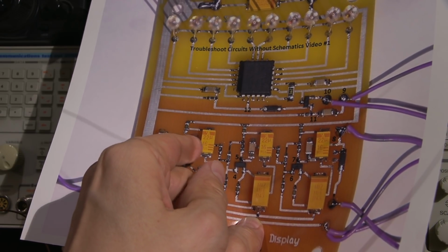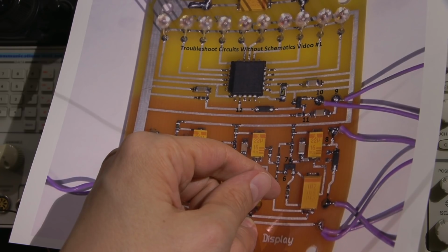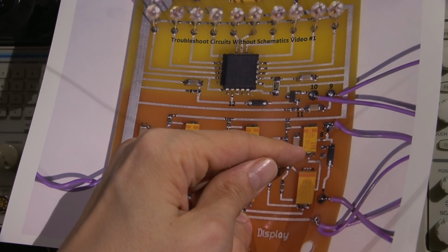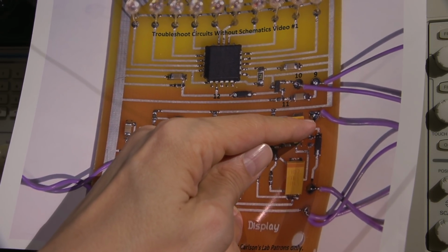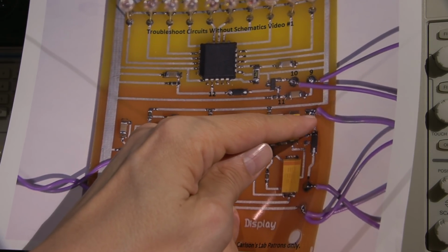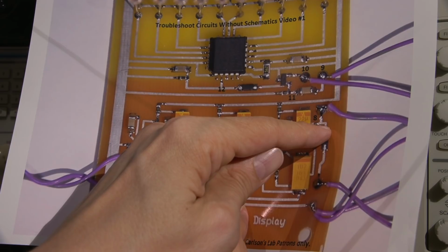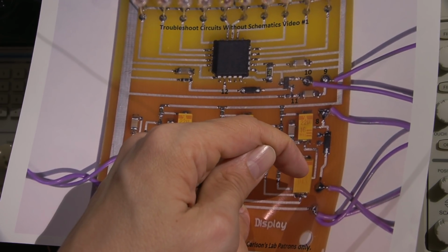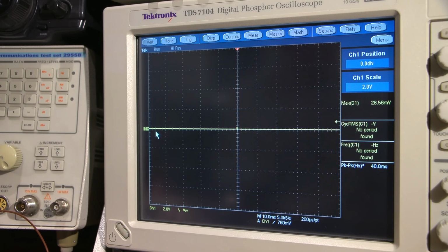So when we're troubleshooting an unknown signal, we want to have our scope on AC coupling. When we have a diode here effectively creating a form of rectification, because we're going to have this being rectified, or we're going to have basically just a positive pulse here, the bottom portion again being clipped off because of this diode, we want to be able to see that. In order to verify that, we need to use the DC coupling on our oscilloscope.